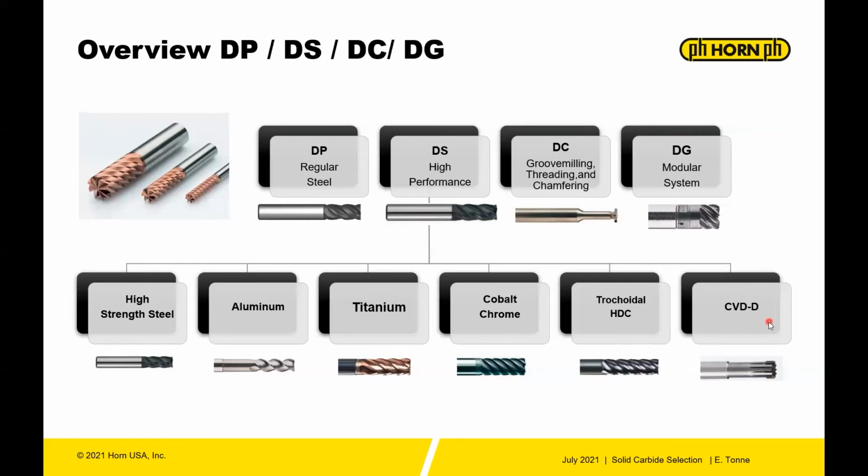And then you also have CVD-D. That's tipped diamond tools for machining non-ferrous alloys, as well as select sintered carbide machining.